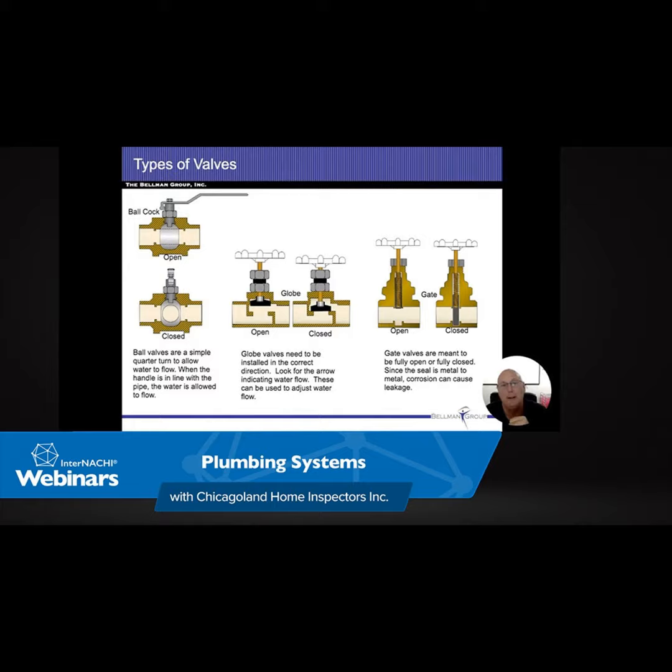I kind of talked a little bit about this before, but now you're seeing a diagram of it. So the sink comes in from the right, goes down, and the vent goes straight up. We don't want that. We want it to go up more like the letter P and go to the left for a foot or 2 or 3. And then we want to get our vent in there so we can let that water get filled up, and then we can break the siphon.